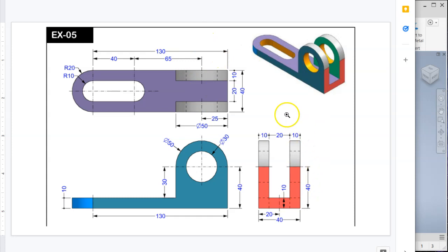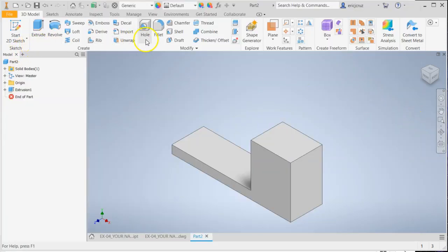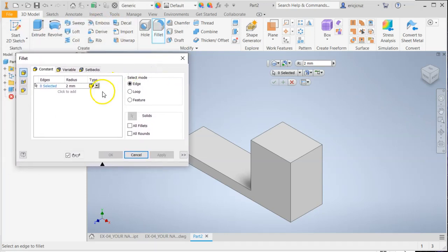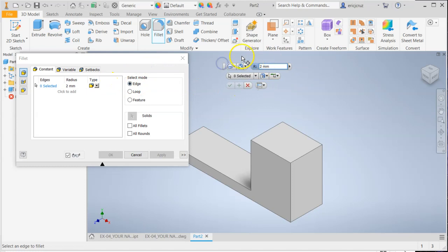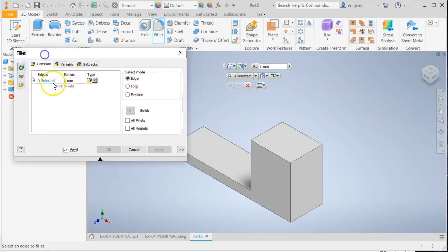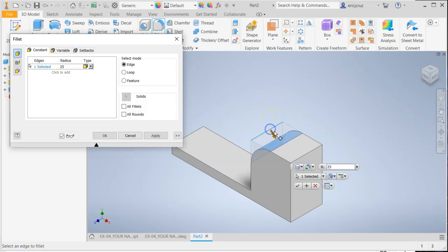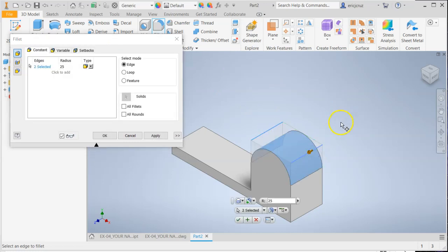Now let's add our fillets. So the outside fillet on this part is going to be 50 diameter, 25 radius. And if you've done this before in the last videos, you'll see sometimes this little menu doesn't pop up. If that doesn't pop up, that's okay. Just go into the actual fillet menu where it says radius and type in the radius first, and then click on the corners that you want to create that fillet on. Okay, so that should work.